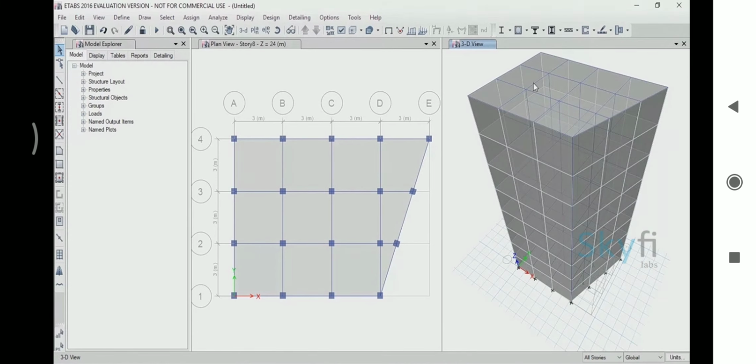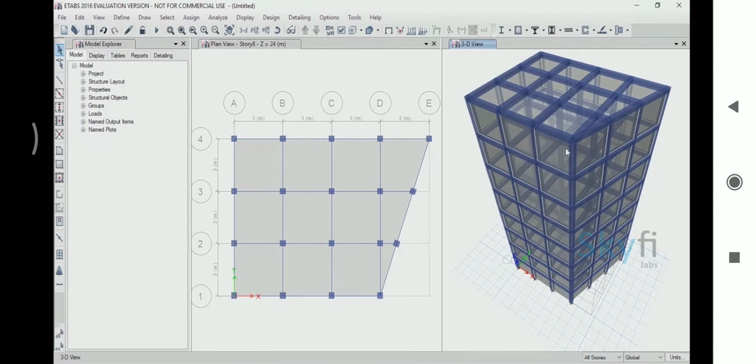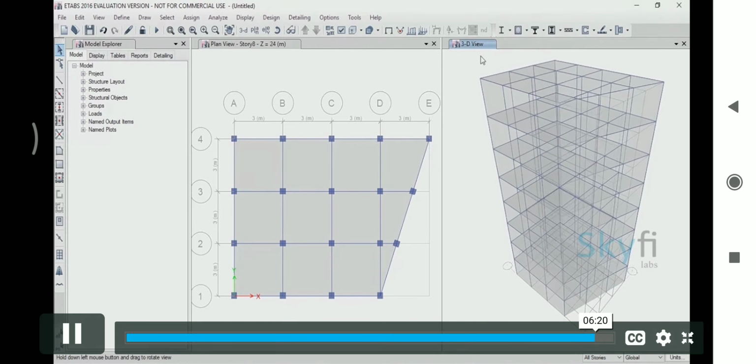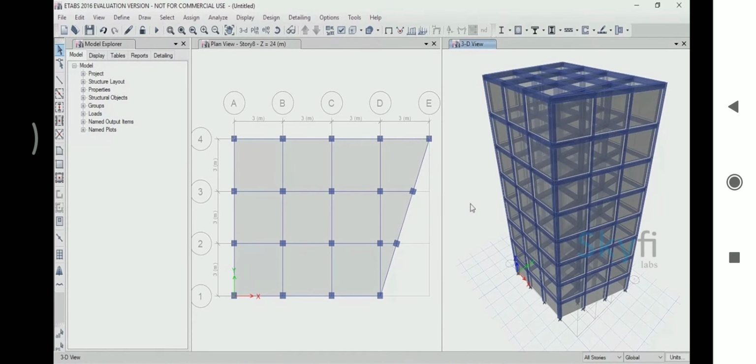There is an Extrude View option in the toolbar, where you can select the Extrude View for Frame Objects option. This will give an extruded view of the beams and columns, in the selected tab. After this, you can go to the steps, like deleting base slabs, and changing joints to fixed, and applying loads to run analysis and design.